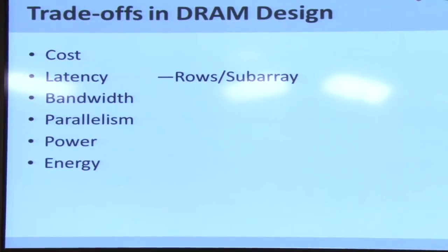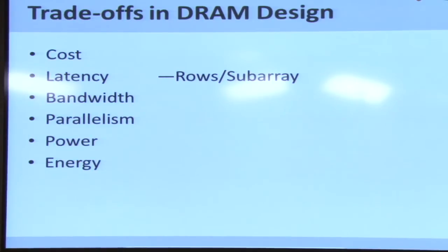Reduce number of pins. Reduce number of pins. What if I wanted to send 64 bits? Okay, I think a better question could be, what if, let's say, I have an 8-bit wide bus, or let's say I made that bus 64 bits wide, right? And if I wanted to send 64 bits in one clock cycle or one half cycle, what should happen internally within DRAM? You should transfer ideally synchronously all the 64 bits, which is hard in terms of timing and alignment. So you're getting there, but what is the problem?